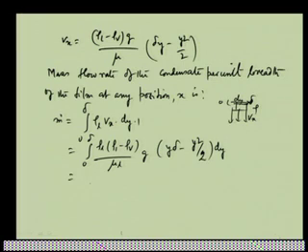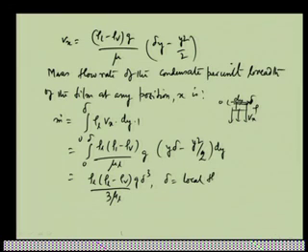So, basically this value comes out to be rho L into (rho L minus rho V) by 3 mu L into G into delta cube, where delta is equal to the local thickness of the condensate film. Okay.